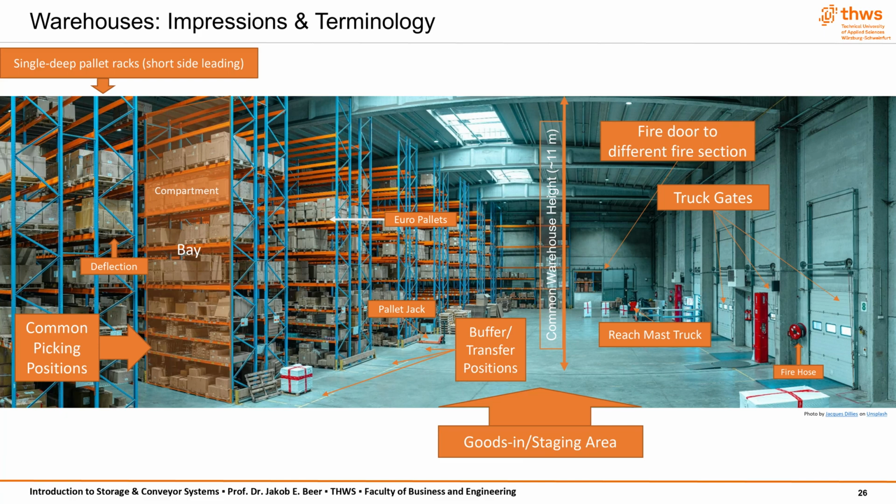This range is quite typical for conventional warehouses designed to be operated with reach trucks or similar equipment. In many cases, 11 meters of clear height has become something of an industry standard, as it allows for 3 to 5 levels of pallet racking while still keeping the top levels accessible to manual equipment without the need for automation. The decision on how tall a warehouse should be is far from trivial. It has wide-ranging implications for almost every aspect of warehouse design and operation.